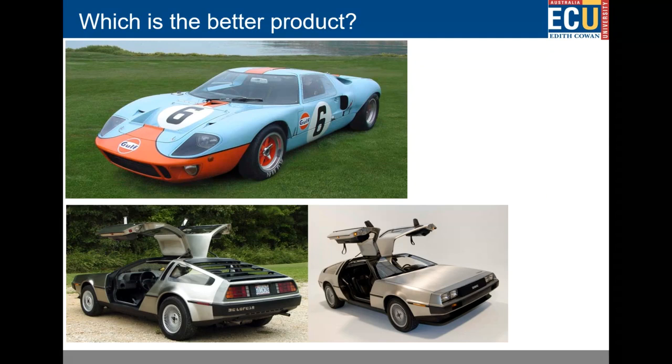The one below that, you may recognize it from Back to the Future. It's a DeLorean DMC-12. There's lots of creativity on this car. It's got gull-wing doors, a fiberglass underbody, and non-structural brushed stainless steel bodywork. It had some new untested manufacturing techniques, things like elastic reservoir molding, which was presumably to help the car be much lighter and lower production costs.